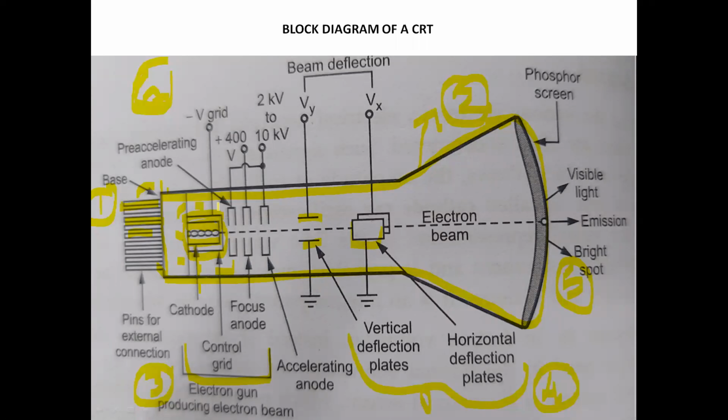So if they keep moving randomly like that without a definite direction, those electrons are to be bombarded on the fluorescent screen. Whenever those electrons bombard on this screen, then only the waveform will be displayed on the screen. But if they are lightweight, to travel from here to this screen, they should have some weight, they should have inertia, and they should be accelerated forward in one direction.